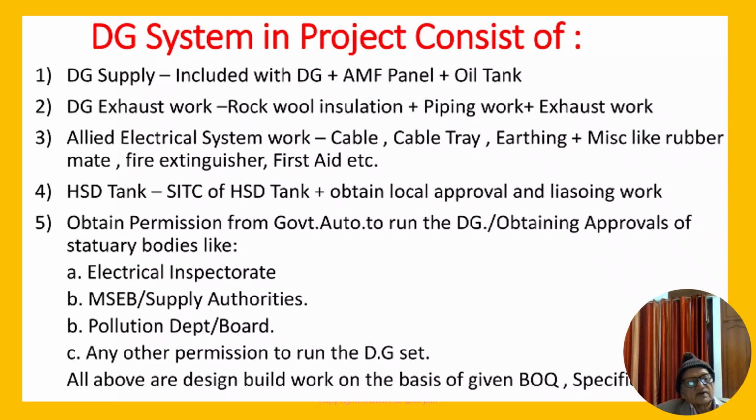Fourth item of design is the HSD tank. You have to take care of supply, installation, testing, commissioning of the diesel HSD tank, high speed diesel. Obtain local approval and liaising work has to be done.